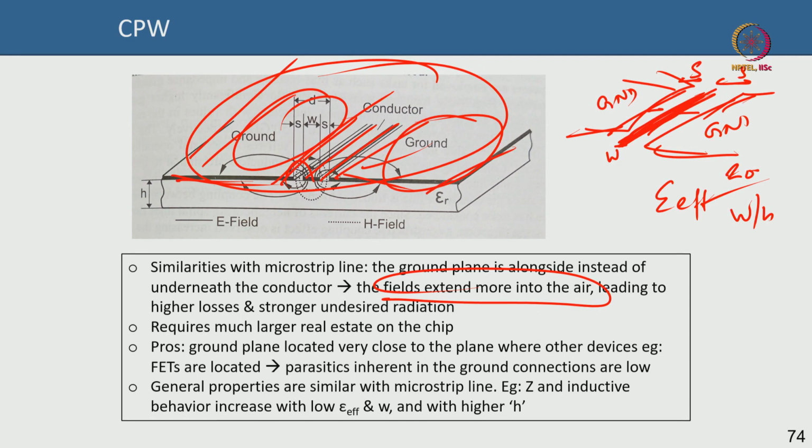As I told you, the CPW line is predominantly for enabling on wafer characterization using an RF probe station or a pulsed setup or a load pull, S parameter, etc. It's to enable on wafer measurement. Once you build the model of the devices, you do not necessarily need CPW pads in an actual MMIC or in a circuit. You can just have the discrete transistor there without these CPW pads, which are otherwise useful for on wafer characterization, and you can implement them in a chip because you already have modeled and understood the behavior of these devices.